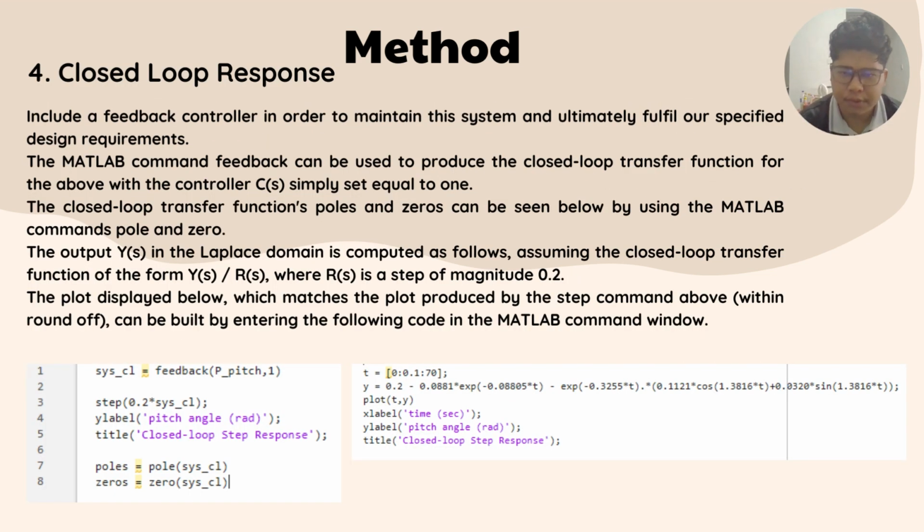Next is closed loop response, which includes a feedback controller in order to maintain this system and ultimately fulfill our specified design requirements. The MATLAB command feedback can be used to produce the closed loop transfer function for the above controller C(s) simply set equal to 1.